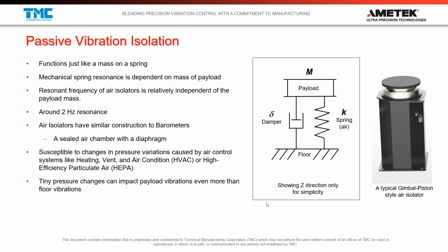A good example is your car spring. If I'm pressing on the bumper of my car, I can drive it at roughly its resonant frequency, roughly 2 hertz. It's going to go up and down 2 times a second or so. And it's highly damped because you have the shock on there. You've got that oil-filled piston that locks into your chassis, and that's helping that car not bounce up and down forever when I push on it.